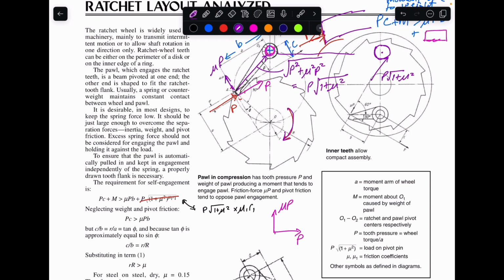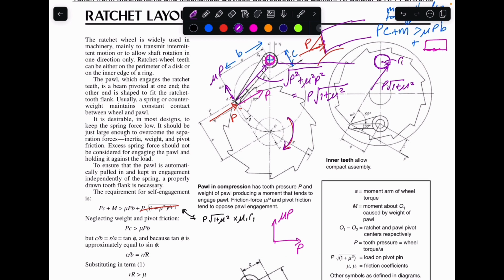And then we have a small radius here, R1, as the radius of the shaft, that pink shaft. That's this here. And then we also have a coefficient of friction, because remember that is sliding about a bush or something. So this friction will generate a frictional torque, and that frictional torque would be this force times mu.